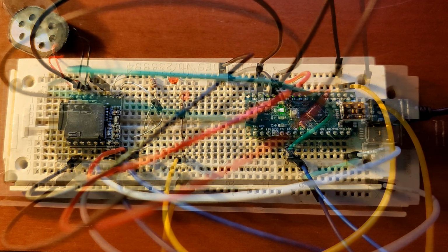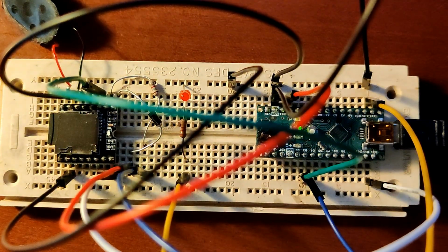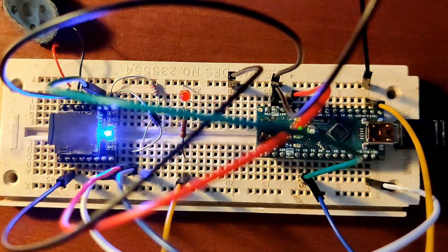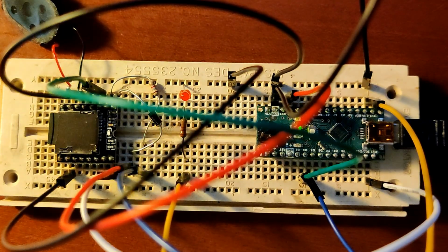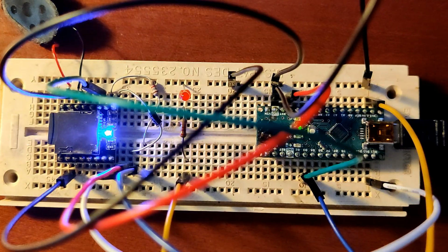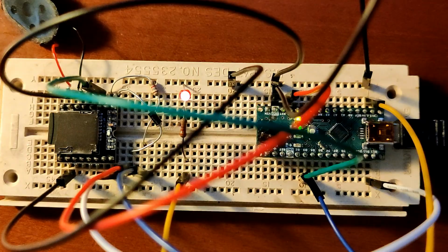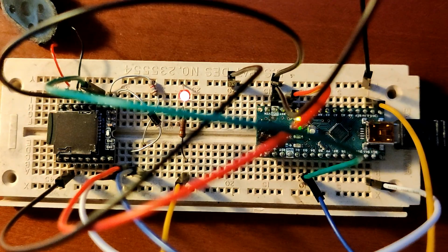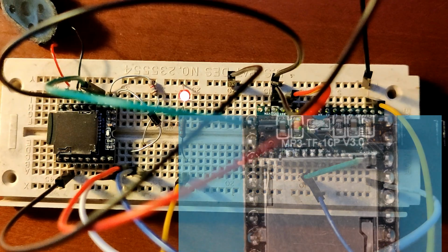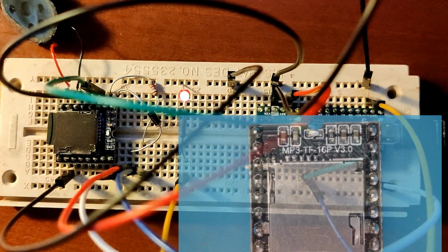No idea why. My general rule has been to get a player with the blue LED. They seem to work the best. I've read in some chats that the JL chip is end of life, so that may be why there are so many variations and probably more to come. As for AliExpress, Amazon, or eBay, I've had some recent luck finding the JL chips. You just need to look for a recent review that shows the device with the blue LED. It is rare that you can trust the actual images of the product. Of course, you can always get a quality device from DF Robot. I would, however, stay away from any 3.0 device with the MH2024K chip.